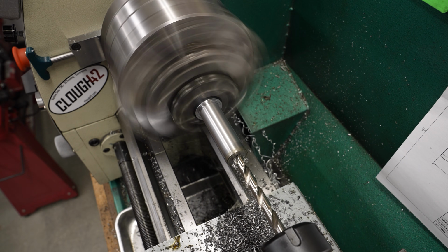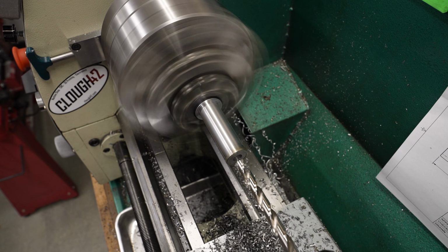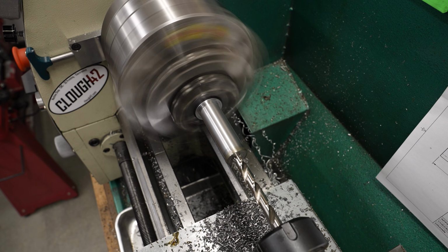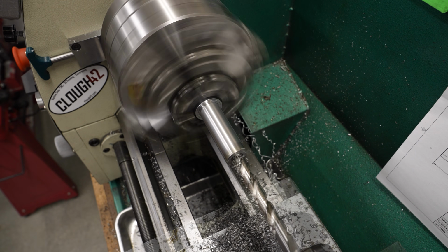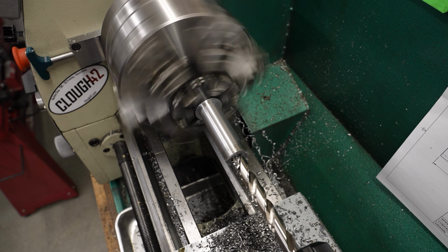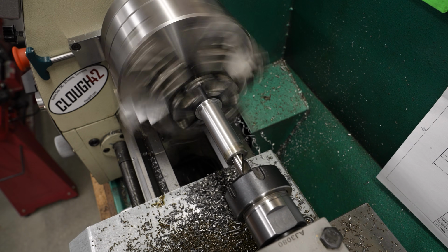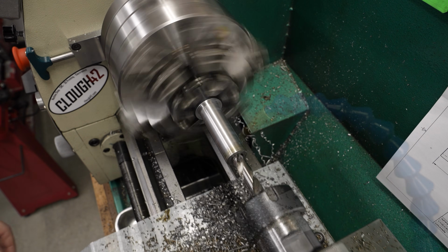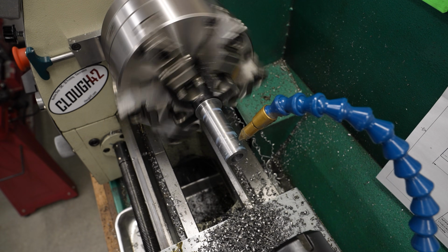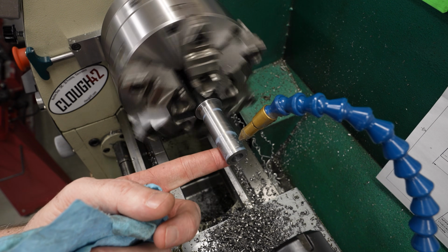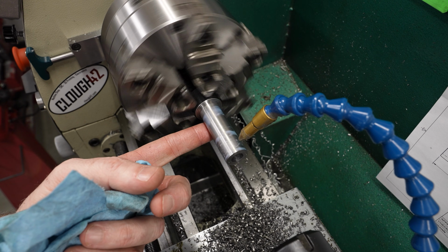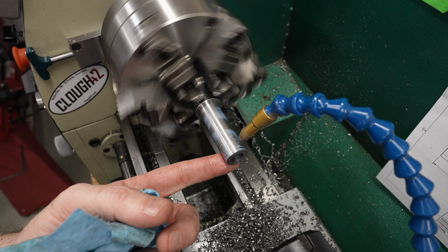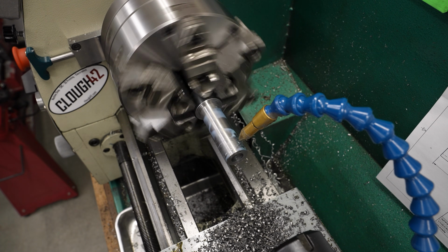Do this in a couple of steps. This is around 3/8. I'm not actually using the 3/8 drill because I don't want to wear that. I'm using one of the drills close to that size, and now I'm up to a size 1 under the 12 millimeter final dimension. I'll put some air and some mist coolant on here just to cool down the part